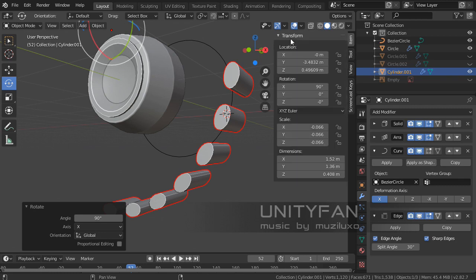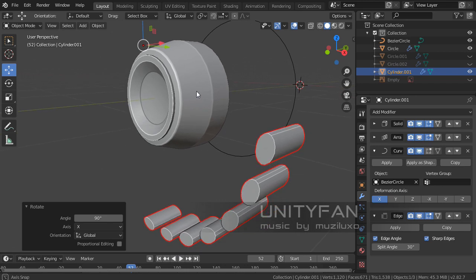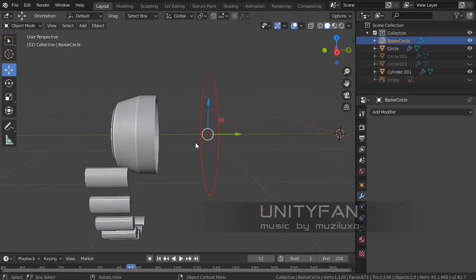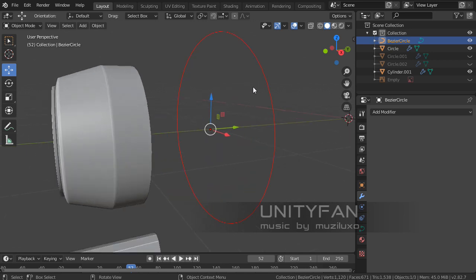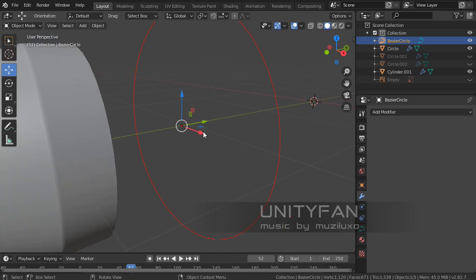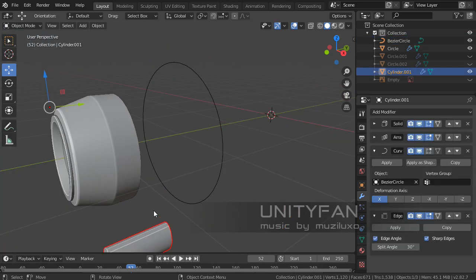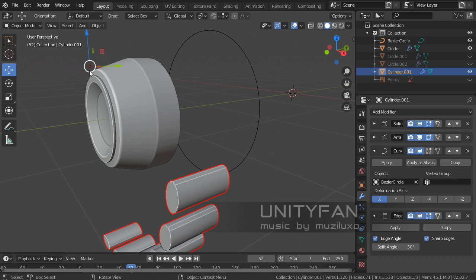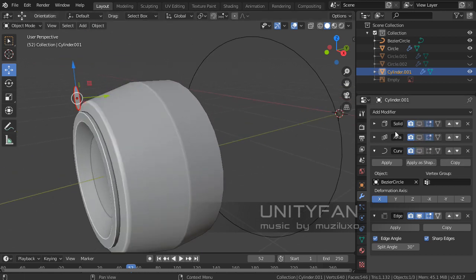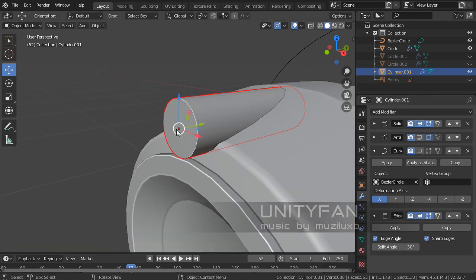This happens because, I didn't know this either, because I didn't use it very often. But apparently the position of the curve origin, this little red dot, and the position of the object with all the modifiers turned off, this red dot, have to match.